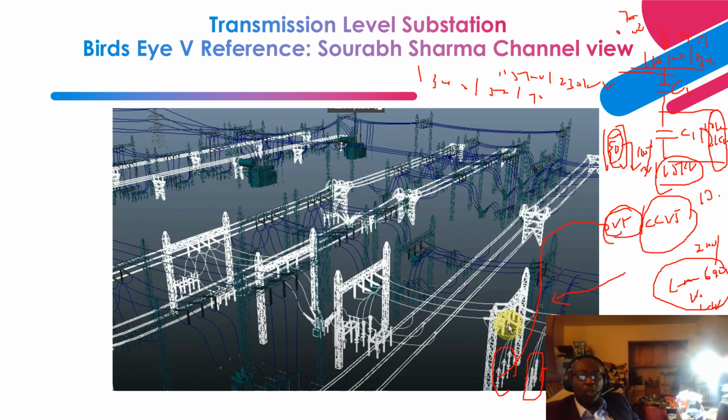On this side, as you can see, those are insulators that protect the conductor from the ground plane. Remember, the tower structure is a ground plane, so the conductors have to be protected from it. Underneath is a jumper that connects to this side. On this side is your insulators, on this side is your insulator, and in between is your jumper, which is installed to preserve the continuity of the circuit.